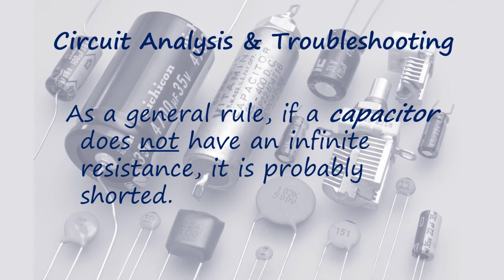As a general rule, if a capacitor does not have an infinite resistance, it is probably shorted.